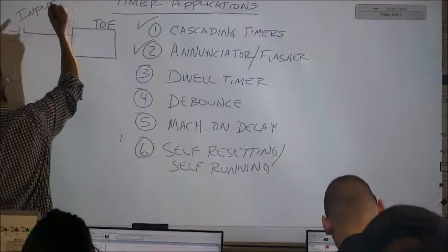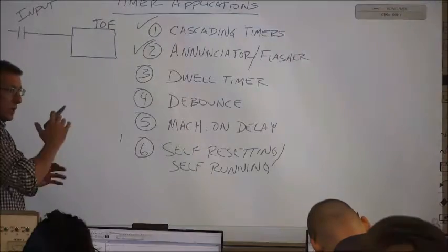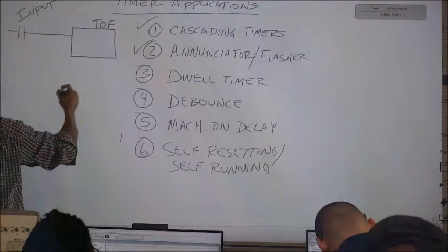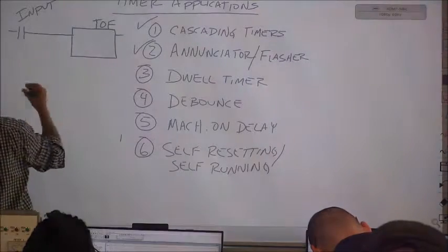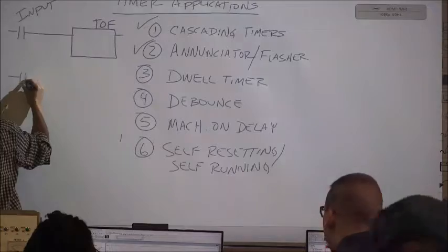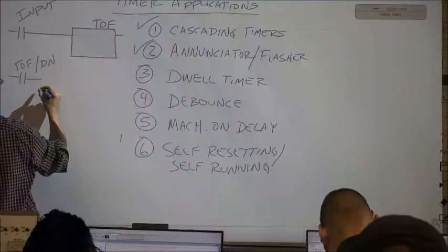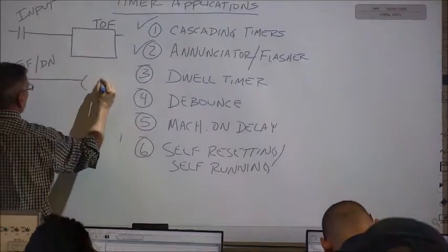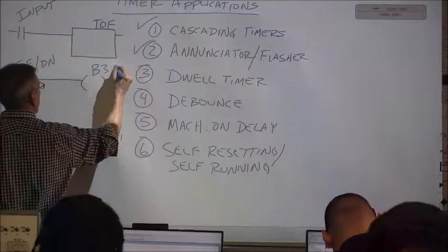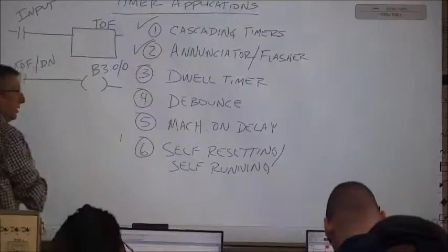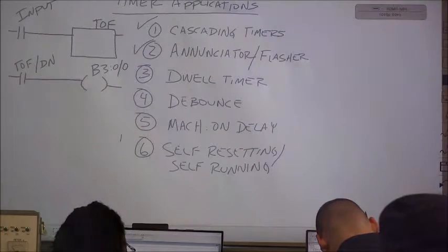Some switch, some physical input that's measuring something, or just to know that there's a part present, or we have a tank full. And then at this point, we use the done bit from the TOF timer to actually say that that switch is good to go. See what can happen there? So as soon as the switch is made,